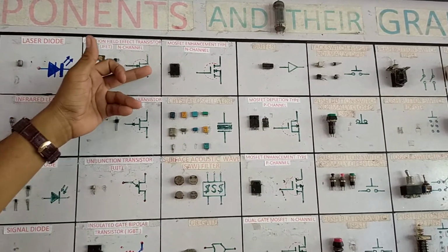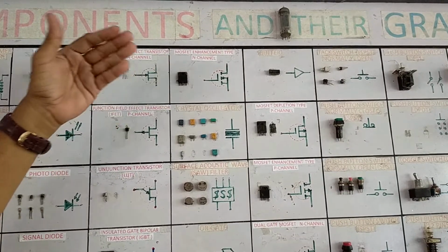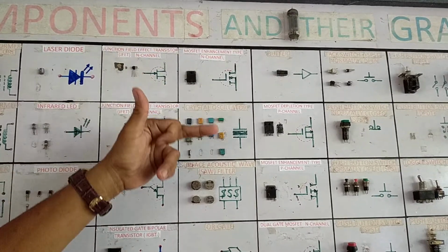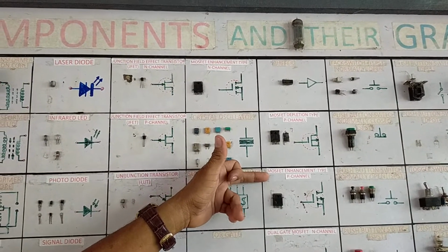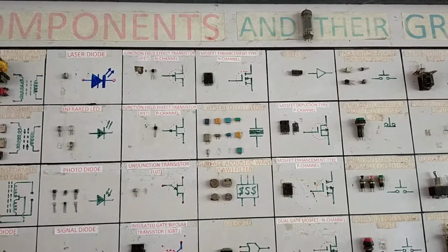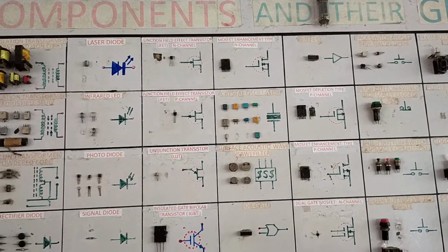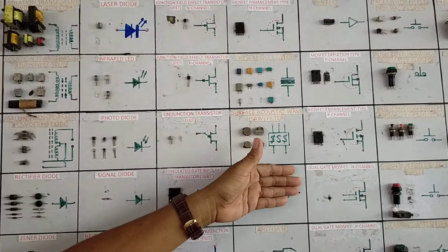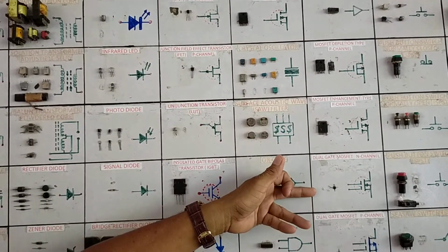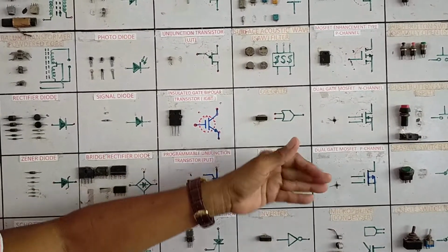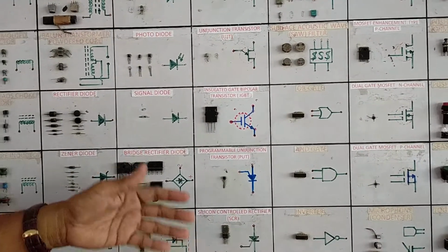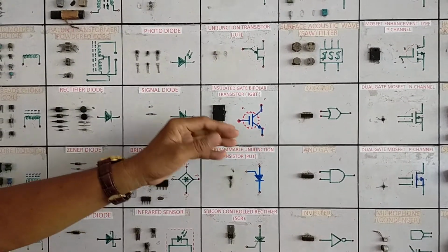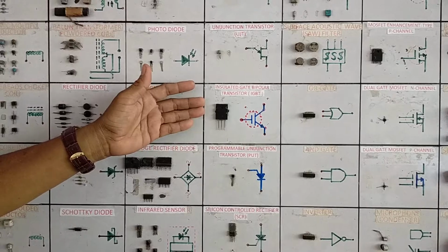Meanwhile, MOSFET enhancement type has two channels also. We have the MOSFET enhancement type N channel and the MOSFET enhancement type P channel. Then, there are advanced versions of MOSFET also. We have here the dual gate MOSFET N channel and the dual gate MOSFET P channel. And lastly, we have the combination of MOSFET and bipolar junction transistor, the insulated gate bipolar transistor or the IGBT.